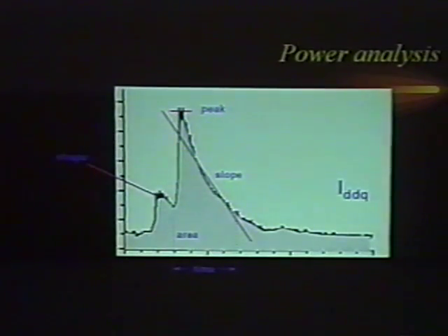Then you might imagine that the Hamming weight, the number of bits that are set to 1, affects the current, because a different number of ones will make a different number of transistors switch, and it will change the power consumption. So we see that there is a correlation between the instruction and the power consumption, as well as between the data and the power consumption.